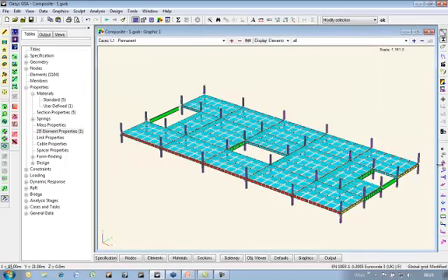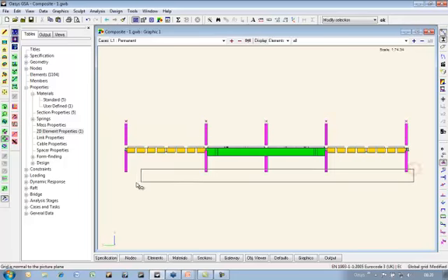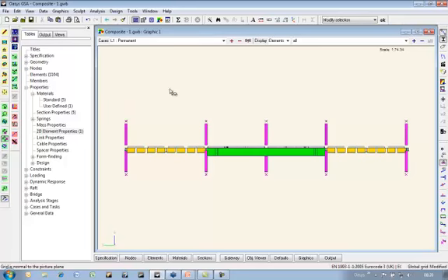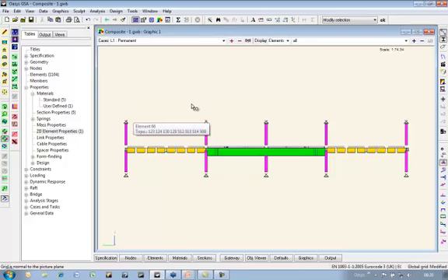We also need restraints. Let me set up the first of all the columns. Now these columns are stub columns. These are half the height of the floor to floor. If I modify those, I can just pin them, because essentially the half height will model half a vibration mode of the columns.